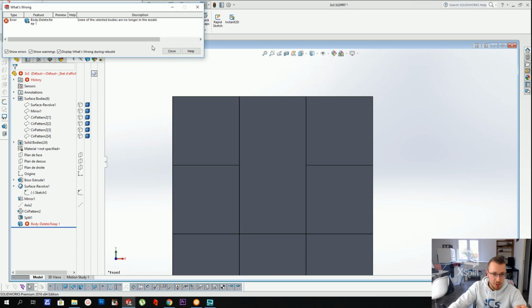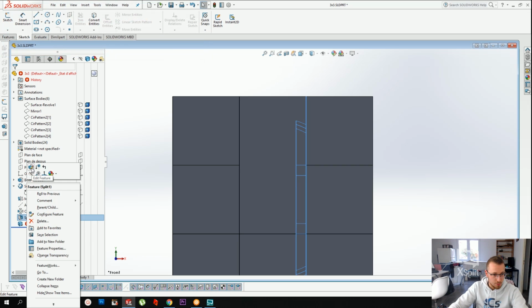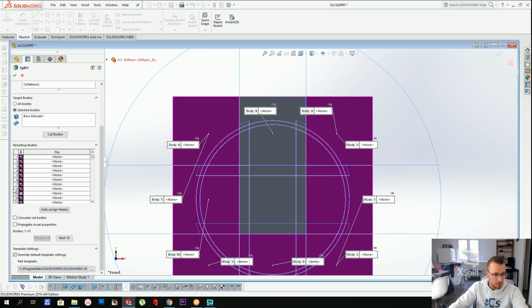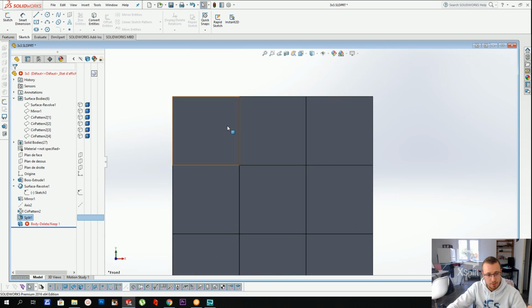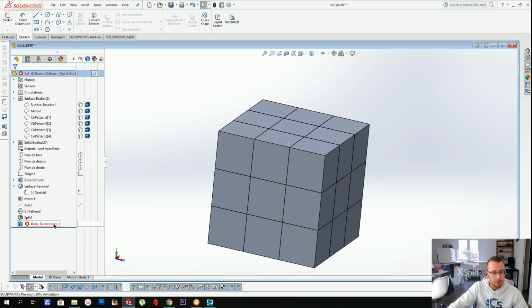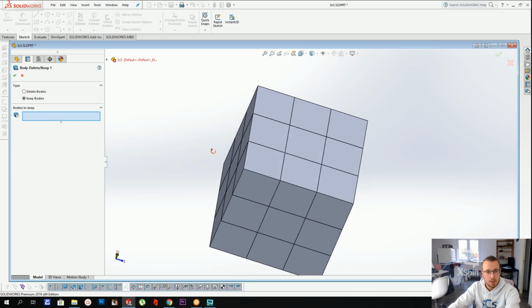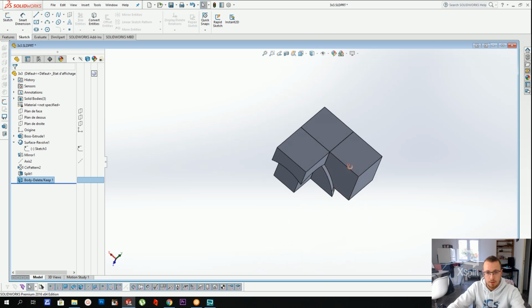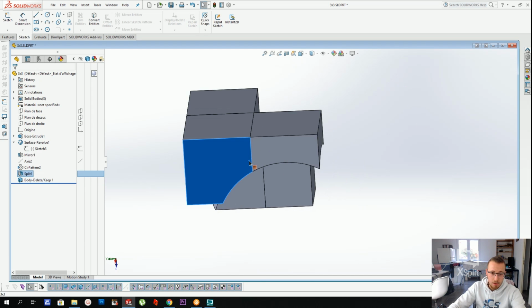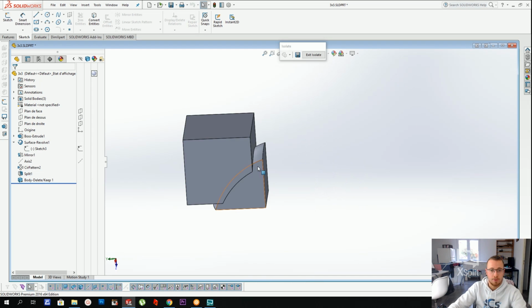And just changing that, let's redo the split, because sometimes when you change stuff in the sketch, the split function doesn't really understand what just happened, and some things can go wrong. So now you're going to re-click on every single body, and it's going to recreate the bodies. And now that you've done that, you go to Body, Keep, Delete, and you're going to click on the three unique parts.